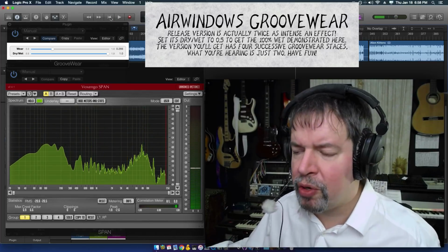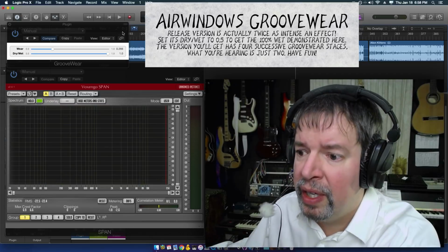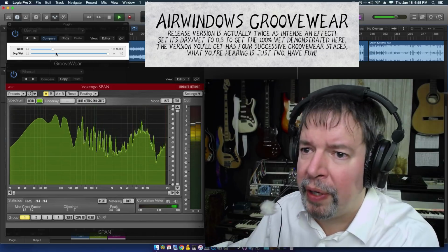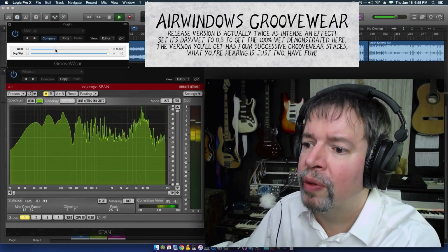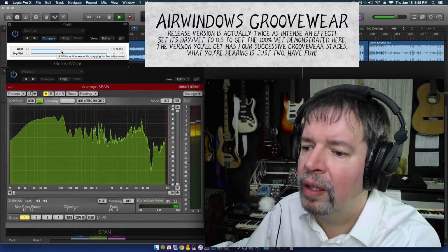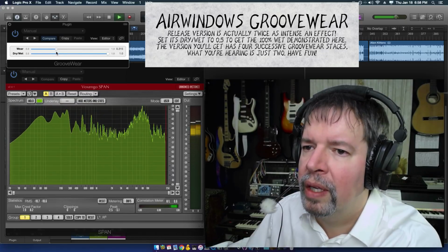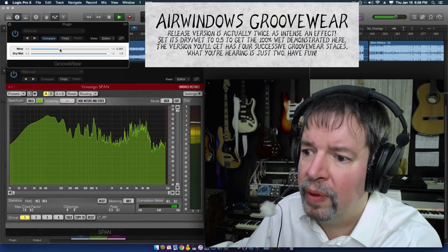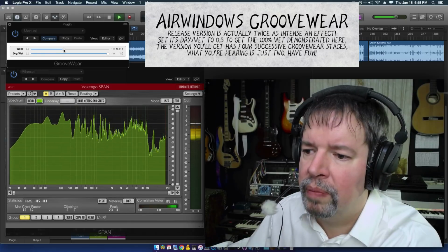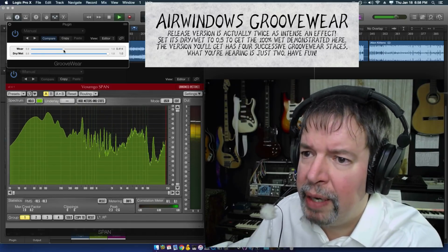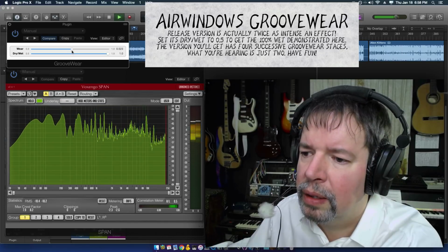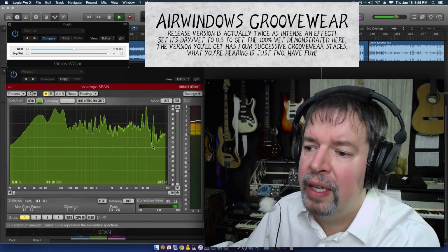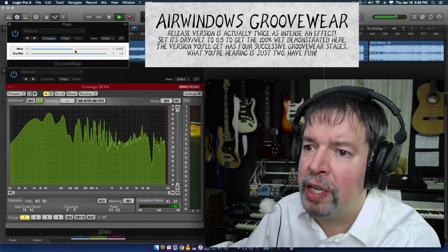And because it's a slew restriction rather than just a high frequency roll-off, there's still a little energy up around Nyquist, brighter than you can probably hear. It'll give it a little bit more life than a normal roll-off. And again, it's doing the same thing that average did, but in another domain. We got this really deep note just past 10K. Around here we have a little place where it's doing its thing, but it's not making one of those deep cancellation notes anymore.